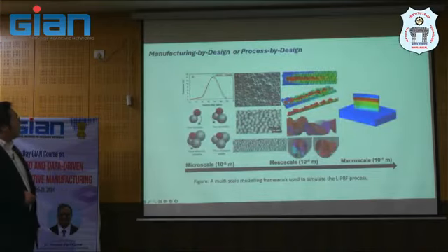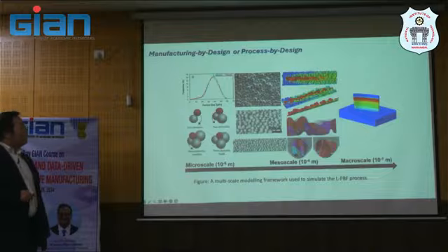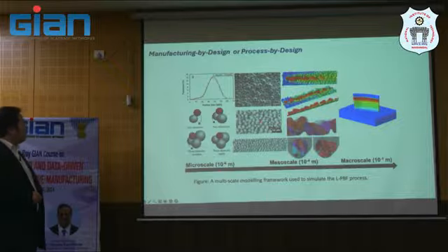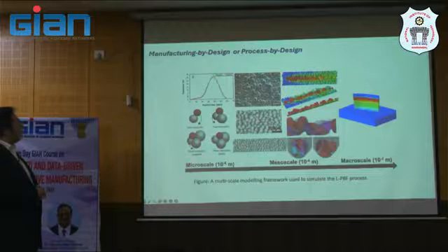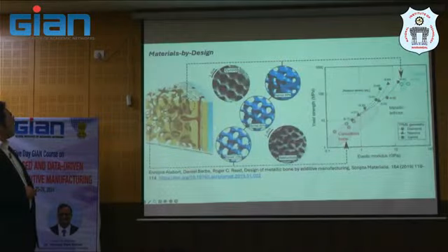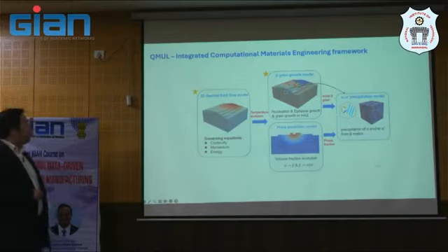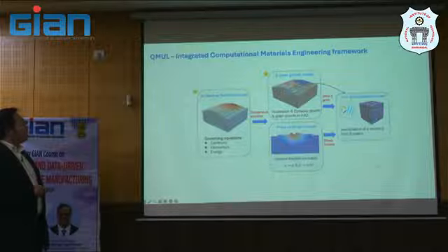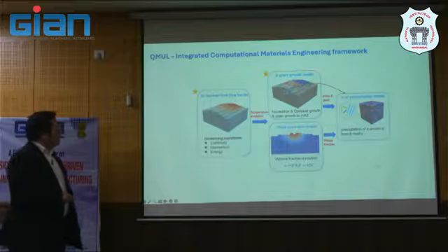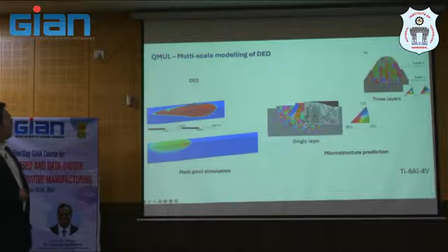And in the backbone of this one, we also run some models in the background. That's why it's actually titanium 6-4, looking at this since 2013 on the particle level, molecule level, microstructure, and macro scale. So we will combine the material by design here with the process by design. So we'll try to use the framework that I mentioned earlier, that we use the thermal fluid flow for the melt pool, and then grain growth model to understand the microstructure, and hence another solid transformation as well. So give you some idea as a picture here.